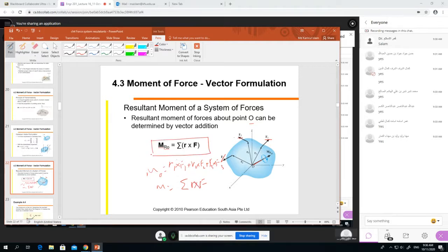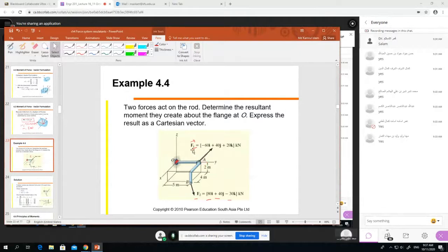So this is our main thing, right? What are RA and RB, or R1, R2, R3? Remember that R is the vector from the point of moment to the point of application of the force, and this is a cross product. For our problem we have two forces, so we have to find the distance from here to the application of the first force, which we call RA, and another distance from here to the application of the second force, RB.